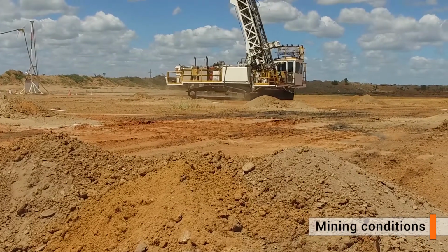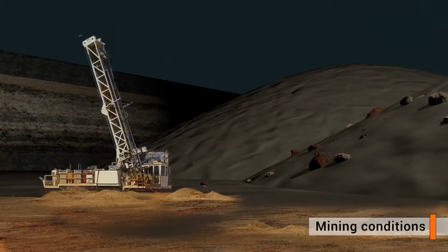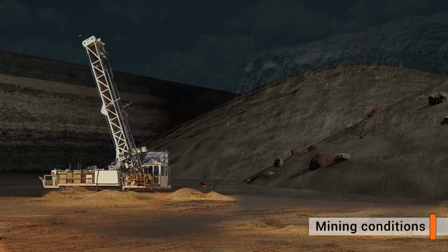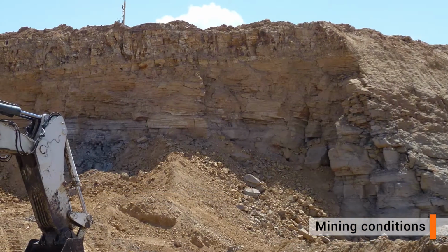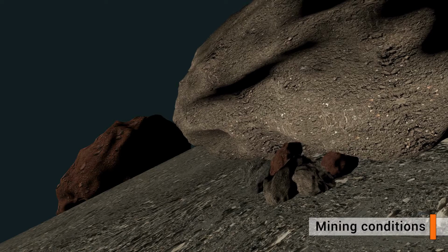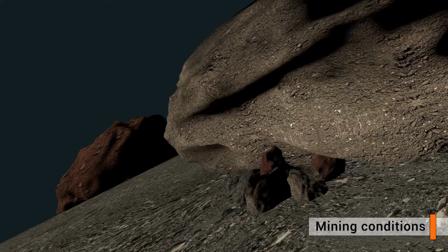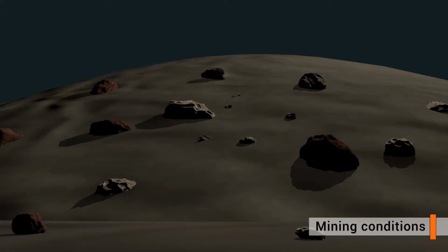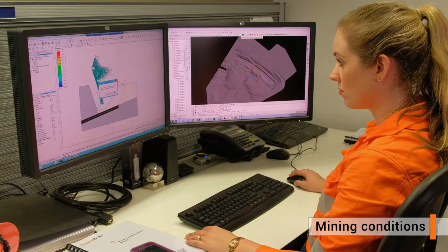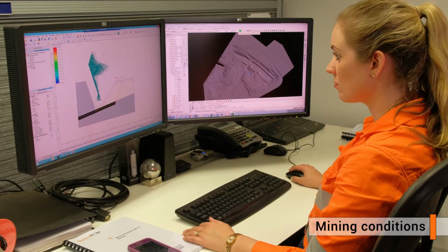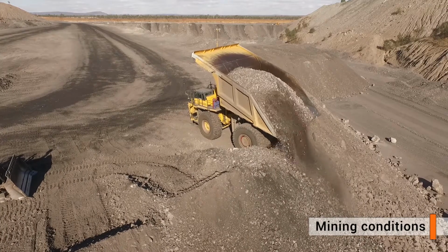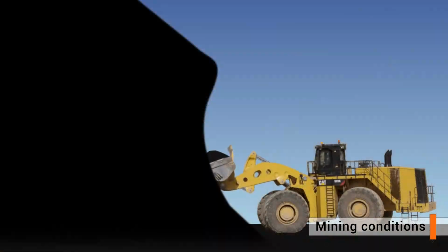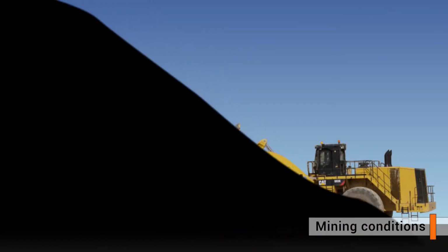Drilling or tramming of equipment next to or in the vicinity of freshly dumped waste slopes, coal stockpiles or excavated slopes that exhibit a jagged face with loose rocks or blocks in the face. Vibrations can result in a rapid loss of cohesion of dumped slopes or coal stockpiles, or cause loose rocks to dislodge in rapid time. Deviating from the mine design without geotechnical review, for example, dumping or excavating past designated surveyed control limits, or oversteepening or undercutting design slope batter angles.